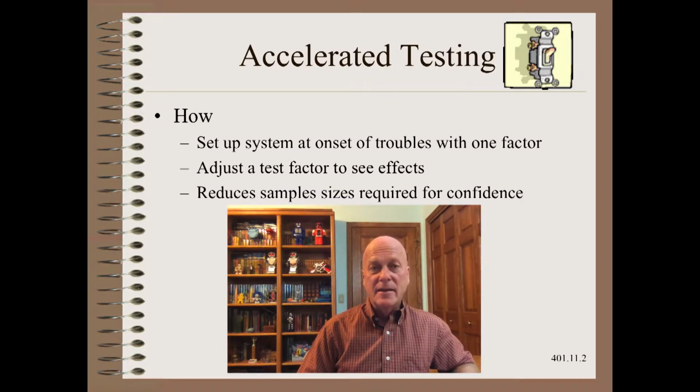One goal of testing is, almost always, laziness. Specifically, the least personal effort to figure out the essential mechanics of a problem. Sometimes it is helpful to set up a system so that it is most sensitive to changes in a knob that we are studying. More specifically, we want the defect or problem rate to be conveniently high, but not too high. The most common term for this concept is accelerated testing.